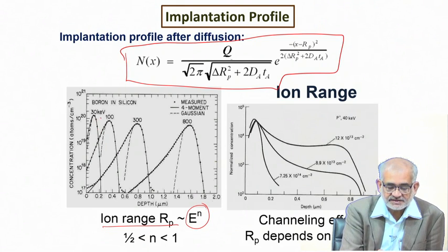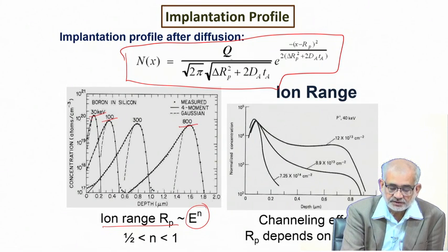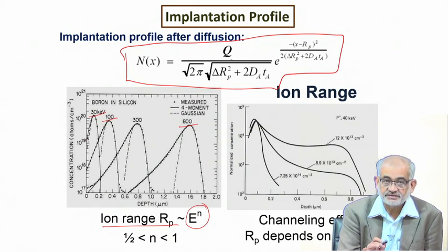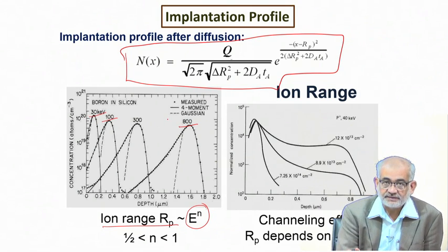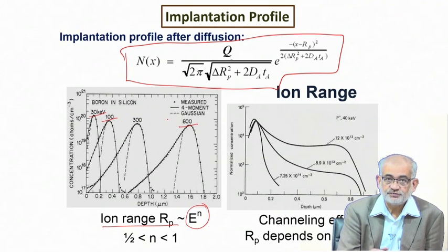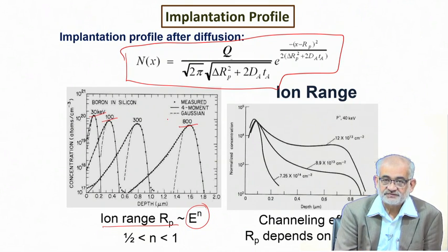As we increase the acceleration voltage from 30 kV to as high as 80 kV, the concentration, meaning the composition per unit volume, is not going to vary much. You apply higher acceleration voltage, you penetrate deeper, so the absolute number of species increases, but at the same time the volume increases.